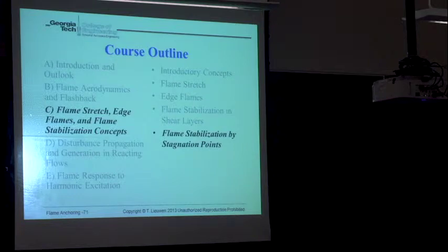Then if I start to think about that in the context of understanding flame stabilization, as I drop equivalence ratio, the local stretch rate starts to exceed the extinction stretch rate. I get holes in the flame. Those holes in the flame will then act like edge flames. And as I keep dropping the equivalence ratio, I get more holes, and then at some point I just completely disrupt the whole recirculating flow that allows me to ignite the flame.